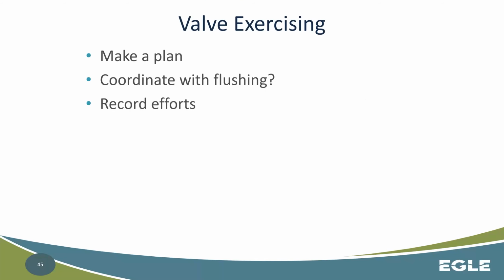So valve turning or exercising, we can use those terms interchangeably. You need to, again, make a plan. It's not very smart to just go out into the distribution system and start shutting valves and opening valves without some sort of plan or understanding of what you're doing. You can go out and start turning a valve and think you're turning it in an appropriate way, and you're actually opening it more instead of closing it, or you're busting valve stems because you're torquing too hard on top, trying to get something to move in a direction it's not designed to move in, right?